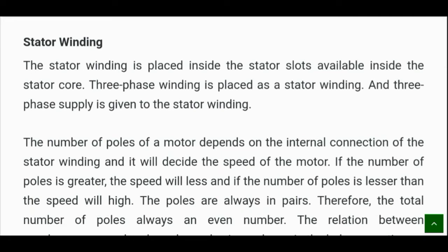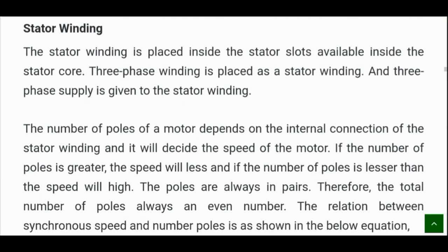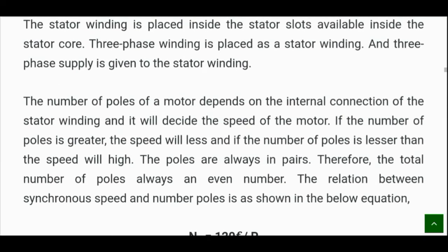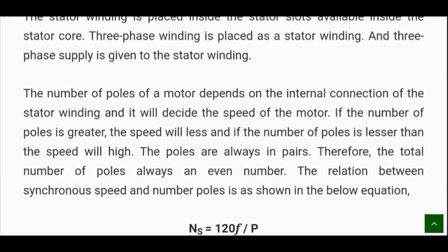Now, what is the stator winding? The stator winding is placed inside the stator slots available in the stator core. Three-phase winding is placed as the stator winding, and a three-phase supply is given to it. The number of poles of a motor depends on the internal connection of the stator winding, and it decides the speed of the motor.